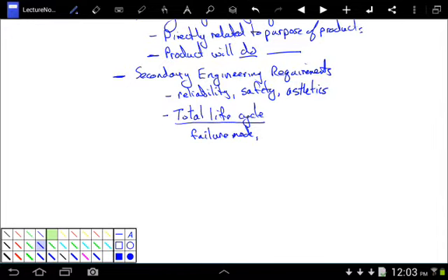And in the case of carbon fiber bikes, by the way, yeah, the failure mode is worse, but one of the reasons that you use carbon fiber is because it's just so dang light, right? Failure mode, fatigue. You have to worry about fatigue if you're using metals, right? Interesting note, carbon fiber doesn't fatigue. Creep. If you're using plastics as a structural material in your product, under constant load, you have to worry about creep, things slowly deforming over time. You have to worry about corrosion, right? How will this thing deal with corrosion, elements, rust?